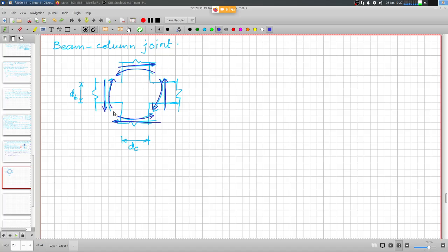So how do I draw the bending moment? There will be a point of contraflexure at the midspan. So the bending moment diagram that I draw, if I draw it on the tension side, then for the columns I can draw this, let's say the center line.